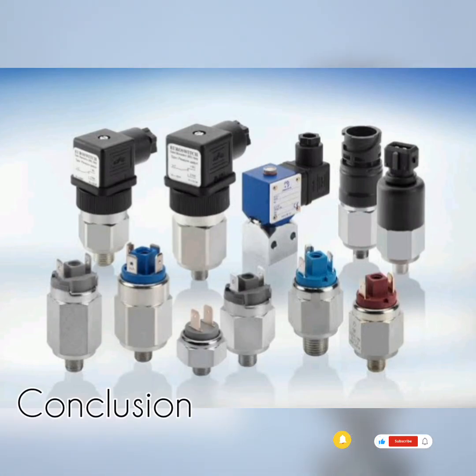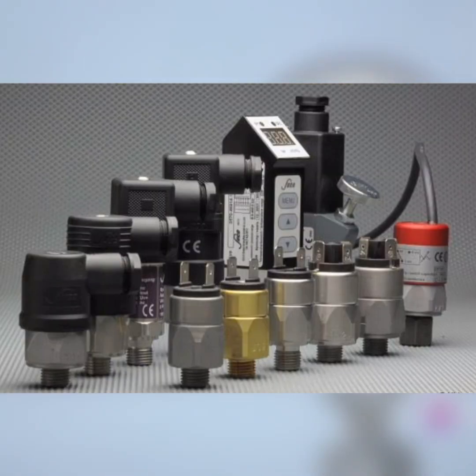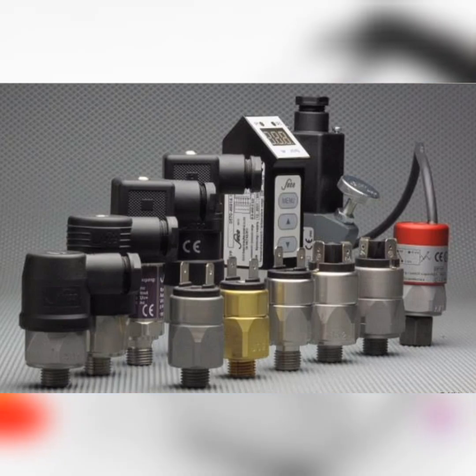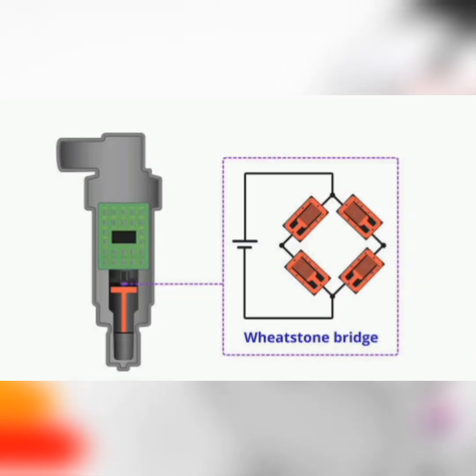These are just a few examples of the different types of pressure switches. Variations exist within each type to meet the specific requirements of different applications. Choosing the appropriate pressure switch hinges on factors such as pressure range, set point, fluid compatibility, and environmental conditions.